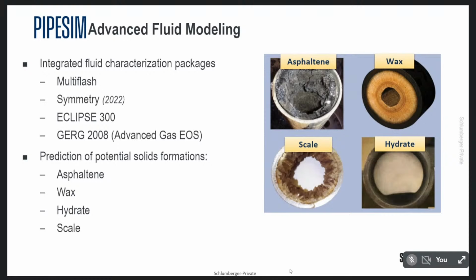If you have a compositional fluid that you would like to model in Pipesim, you can add the components and Pipesim will create the phase diagram for you natively. We have several fluid characterization packages. Multiflash has been with Pipesim for many years from KBC. And when you install Pipesim, Multiflash comes with it. Of course, you will need a separate license for it.